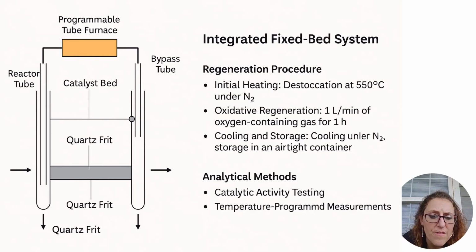Cooling and storage: upon completion, the catalyst bed was cooled to room temperature under a nitrogen purge to prevent recontamination or over-oxidation. The regenerated samples were then unloaded and sealed in airtight containers for further analysis.